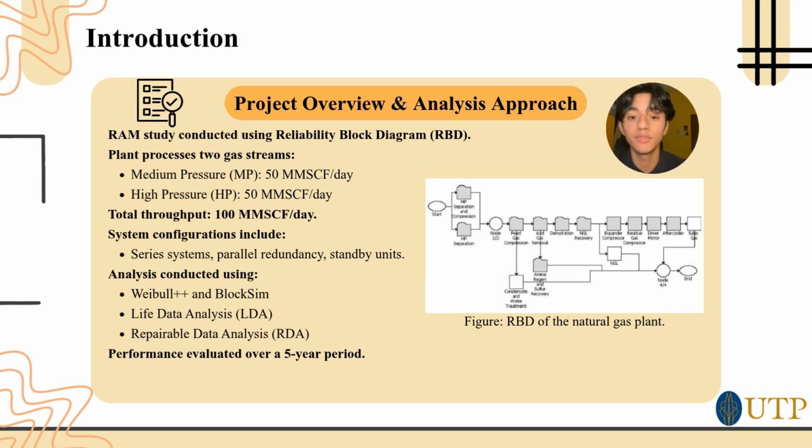The system includes different configurations such as series systems, parallel redundancy, and standby units, which all influence the overall system reliability and availability. To evaluate the system performance, failure and repair data were analyzed using Weibull++ and BlockSim. Life data analysis and repairable data analysis techniques were applied to assess the plant's performance over a 5-year operational period.